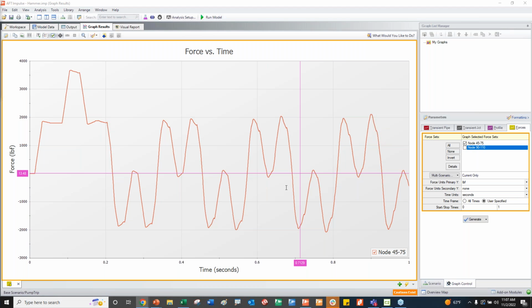I don't think spectrum analysis is obsolete. It's useful, but we have to understand its limitations versus time history analysis. In my case, I prefer to do time history analysis, but spectrum analysis is also useful, especially if you have dynamic isolation by anchors, so that one force doesn't affect the other.